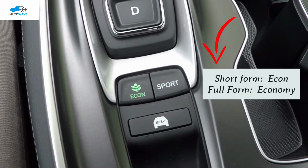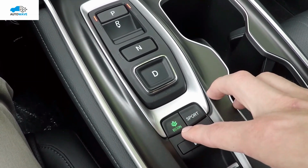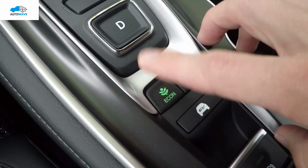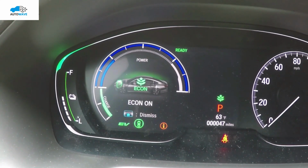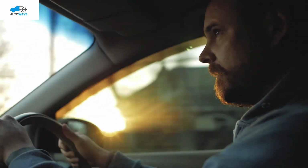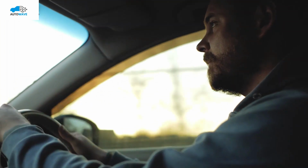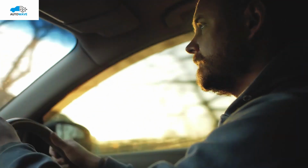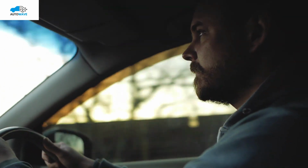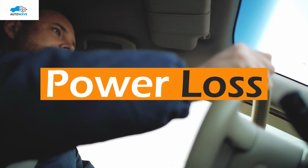The word econ comes from economy, which is relatively used as fuel average. You mostly see this button in Honda CVT cars. Econ mode is a drive mode that depends on your vehicle's overall efficiency. When you activate econ mode, your car's fuel average increases, and this happens because your engine's power is reduced, which makes your car consume less fuel. Where your car normally travels 15 kilometers per liter, when Econ mode is activated, it will travel 18 kilometers per liter. The most noticeable effect when pressing the Econ button is the reduction in power.